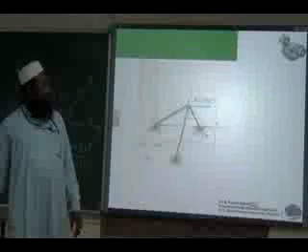So this force F, 300j Newton, is the given force. We resolve it into two forces, parallel to AB and perpendicular to AB. So first we find the position vector for AB. So we have to find the coordinates for A and B.